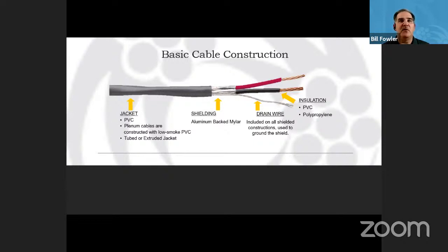So again, in this class of cable, depending on the structure it's used in or the type of use, you'll see these different constructions from PVC all the way up to tube. That's where you'll see some of the cable has a loose construction. You'll actually see some data cables where the extruded jacket is a little bit tighter, so you have to be very careful in stripping the cable. That's one thing that you'll see in the tools out there. There are special strippers made for stripping low voltage cable, because the jacket is really soft, really thin, and the way the pairs come up against the jacket, you can actually cut a pair. So that's something you have to really consider.